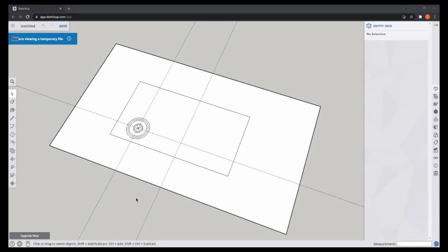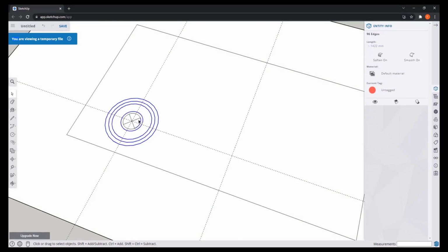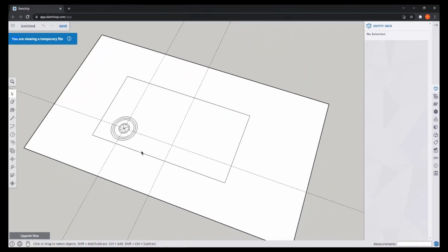How to select objects inside the face. Now let's look at this example. I want to copy these circles to the intersection of the next guidelines. Clicking on each object one by one just takes a long time. So the best is using a selection area. However, if I open the selection from right to left, look that I select everything that is touched by the area, so it doesn't work.